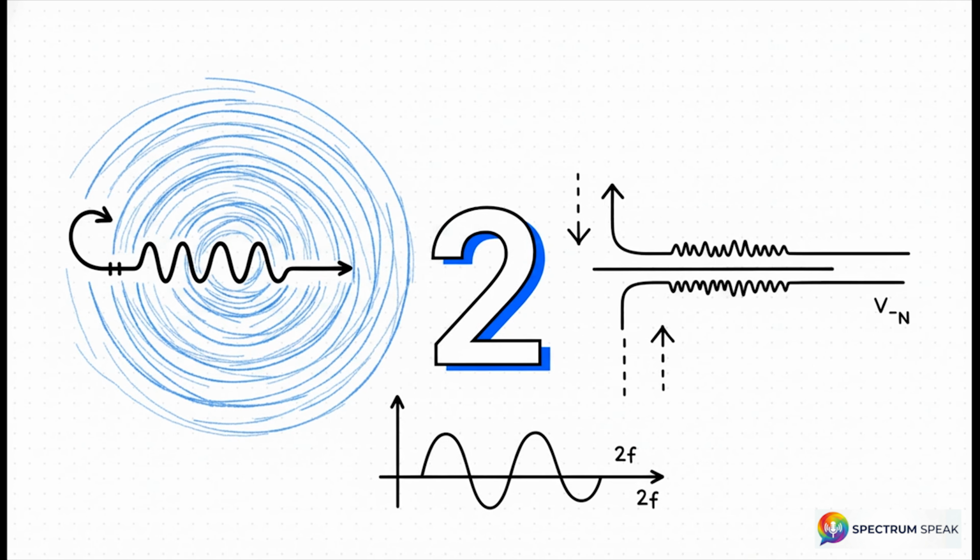But hold on, here is the absolutely critical multiplier. That omega term in our equation, that equals 2 times pi times frequency. So what does this tell us? It means magnetic coupling is directly proportional to frequency. If your interfering current doubles in frequency, your induced noise voltage Vn exactly doubles. Literally, higher frequency signals create proportionally worse magnetic interference. You have to watch out for that.